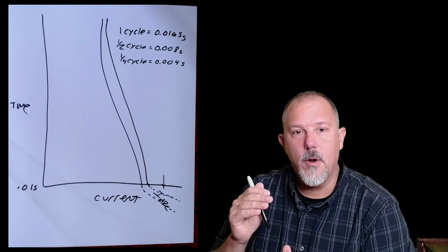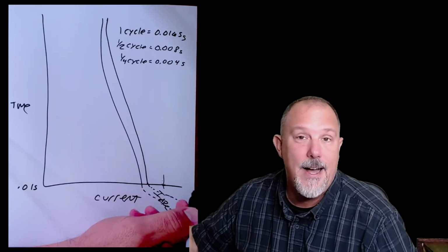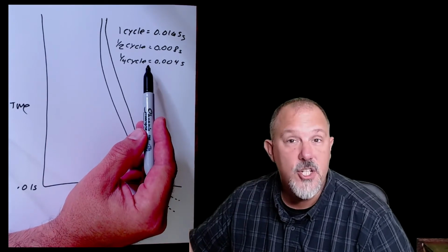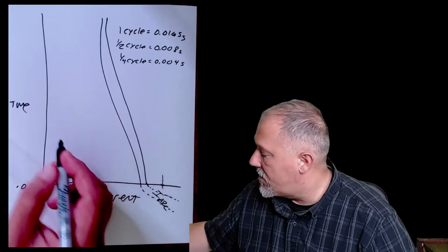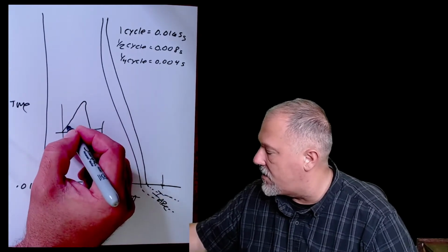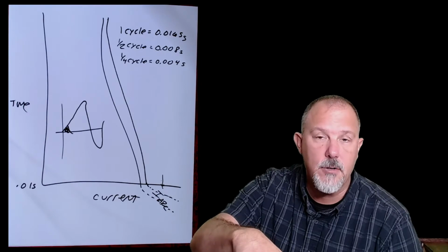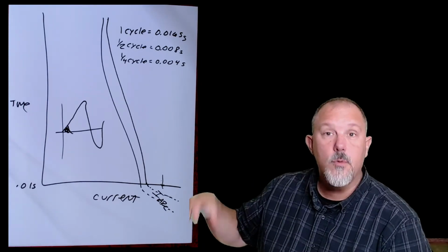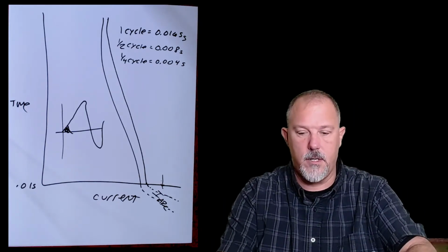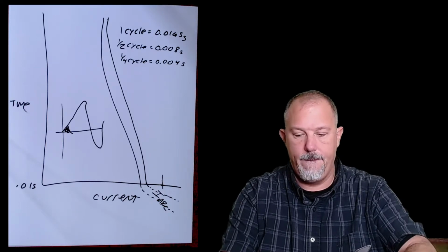So for this example, if my arcing current is over in this region or higher, I'm going to be clearing that fault in its current limiting region. That means that arcing current, instead of seeing something that looks like this, I'm going to only see a little blip. I'm going to reduce the forces on the power distribution system, and I will reduce the incident energy.